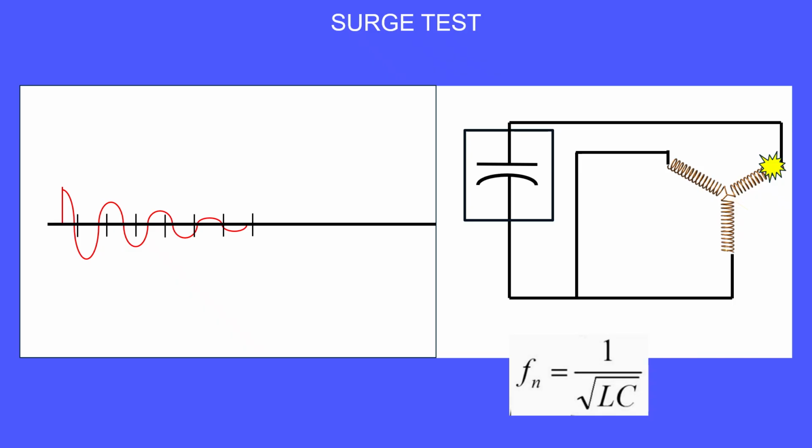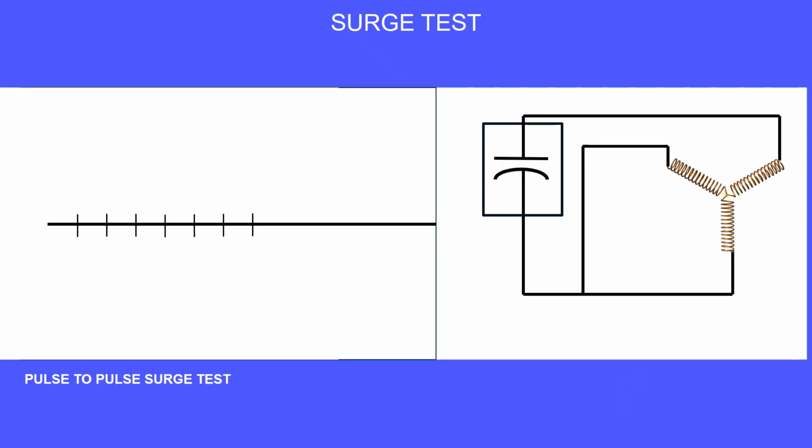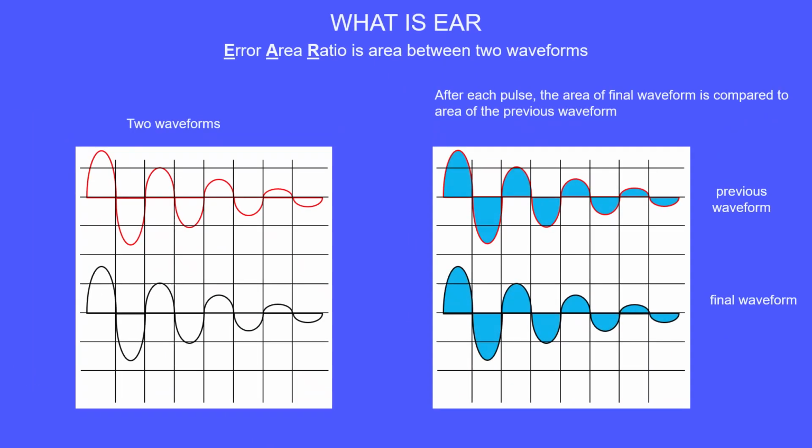The test will start out at 0 volts and with each pulse increase voltage slightly until full target voltage is accomplished. The test compares the waveforms between pulses to confirm the ring frequency hasn't shifted. The test set can compare the ring frequencies two ways, line to line or pulse to pulse.